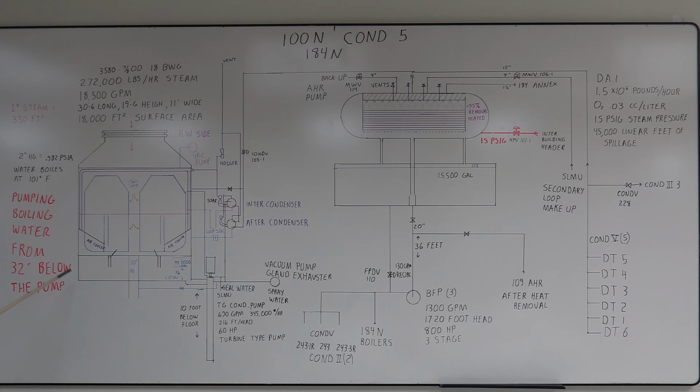The way this was laid out is, I remember where the condensate pump sat. The water would come in the backside, so we're looking at the water box return part of this. The water would come in this set of tubes and be coming out towards us. It'd flip around and go back, and then this would be your outlet on the water box side.